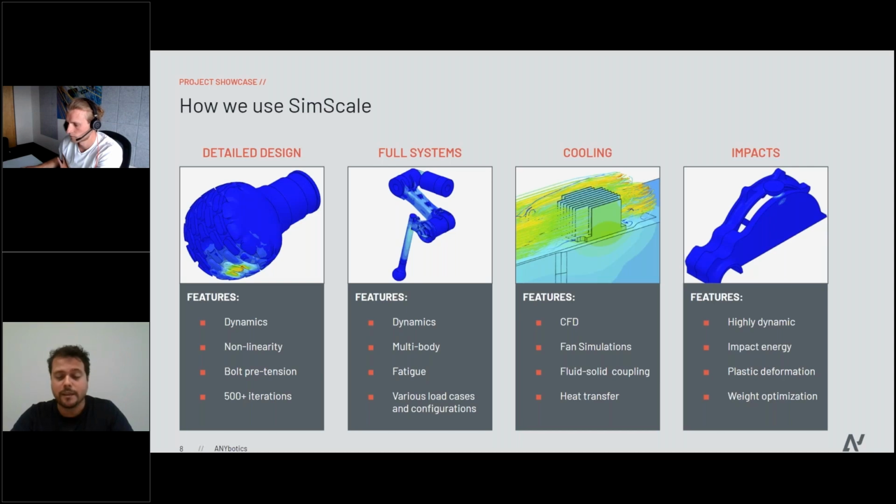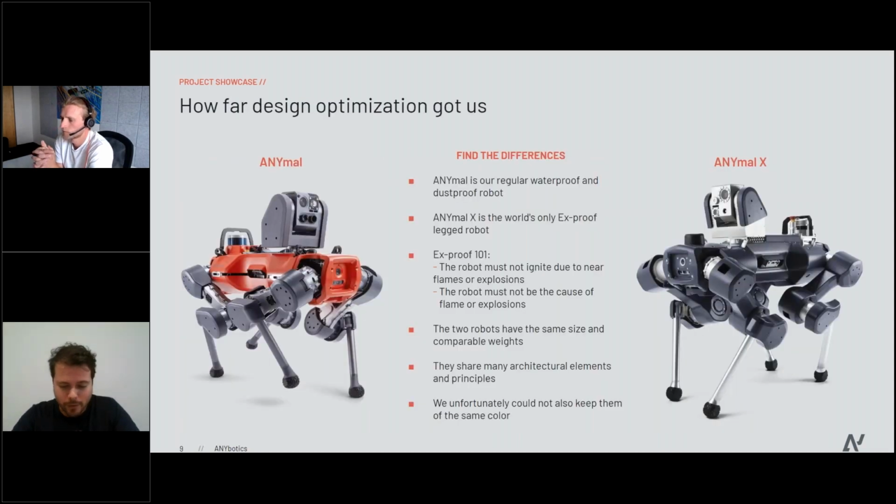And what we did is, instead of running the test over and over again in-house, we developed an FEM model, we validated it against our tests, and then we used the FEM model to iterate our design until we were happy with it. So in this way, we optimized how much money and how much time we were investing in testing the design, instead of simply going for it every single time, right?